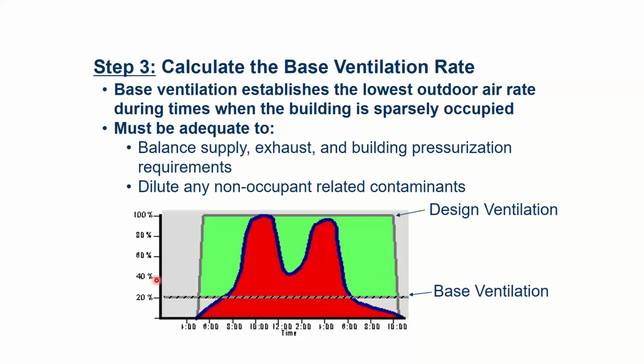62.1 got modified in 2004, and hence the mechanical code in 2006, they gave me the base ventilation rate. That's the whole entire reason they separated the blended per person number into a per person plus per square foot number. The square foot number became my base ventilation rate. And then my total number was the base ventilation, square footage, plus per person. And they essentially said you can modulate between these two numbers. That is the only reason we separated in the ASHRAE standard, to make you do math, because that's fun, and then to allow demand ventilation more easily.